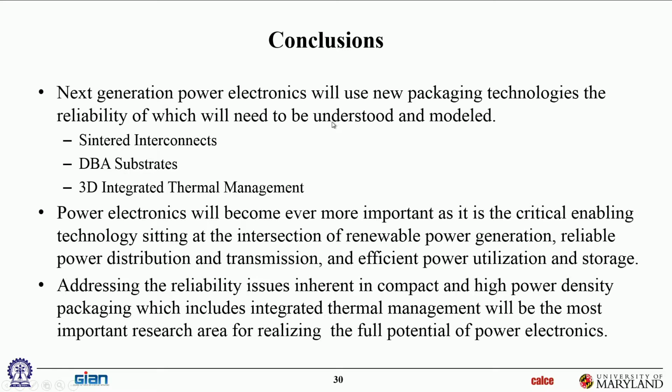And then people are talking about high temperature, high band gap materials, switching over slowly to gallium nitrides, which have their own set of challenges because gallium nitrides have much higher defect densities, dislocation densities, than silicon does. So that unfortunately affects the electrical characteristics. They call them threading dislocations, and they evolve because of the high stresses. The dislocation density grows over time, and slowly the electrical functionality drops off. So gallium nitride has its own set of issues, but you have the advantage of wide band gap materials, so those are getting more and more popular.